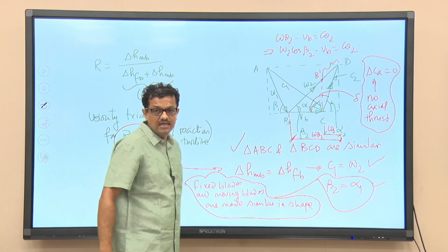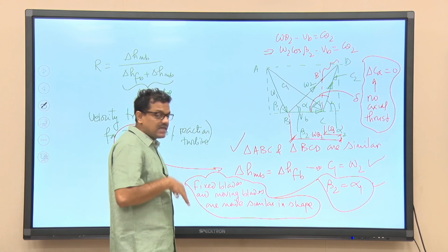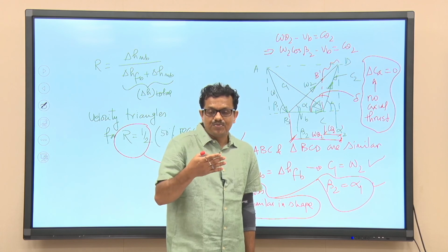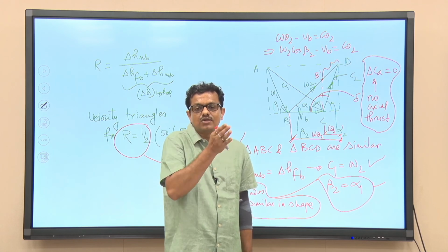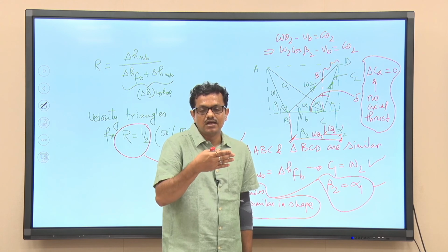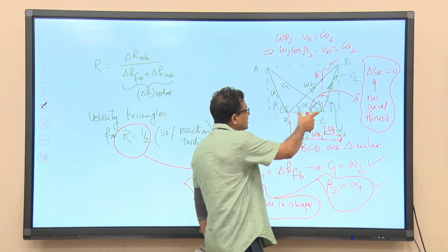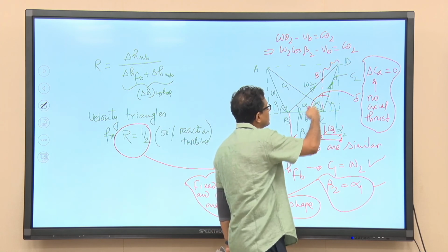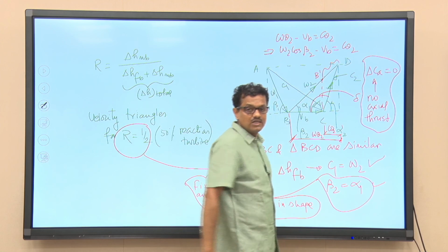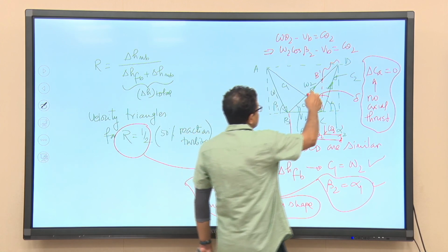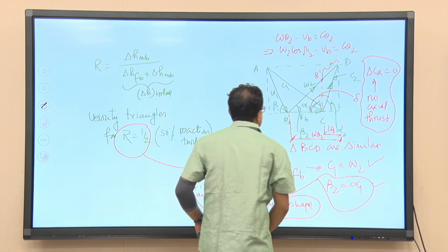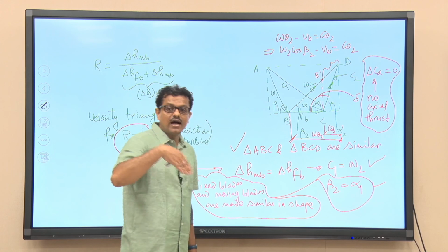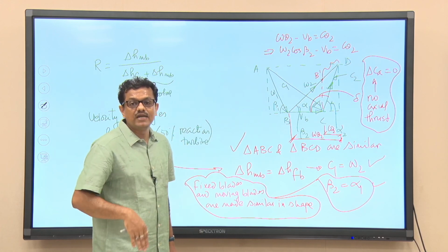As we have discussed, because the shape of the moving blades is a nozzle shape, when steam is passing through the row of moving blades, kinetic energy will increase. Now, if we draw the velocity triangles, C2 will increase compared to C naught, and as Vb remains fixed, the resultant, that is the relative velocity, will increase, right. So, W2 will be higher than W1, and as a result you will get the reaction force.